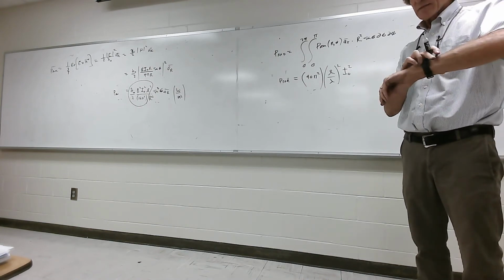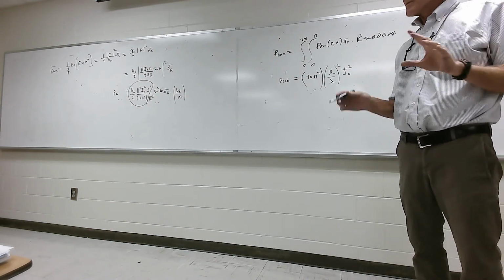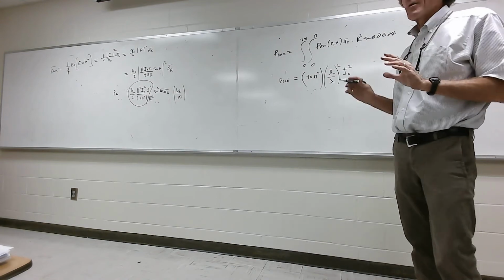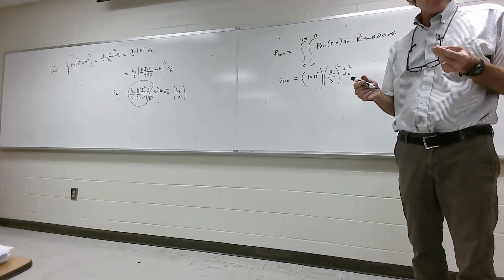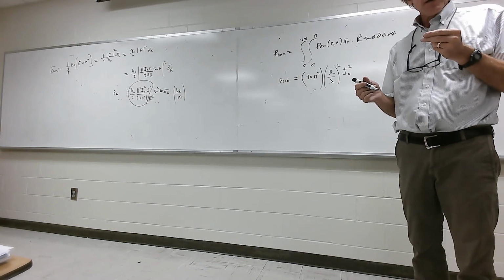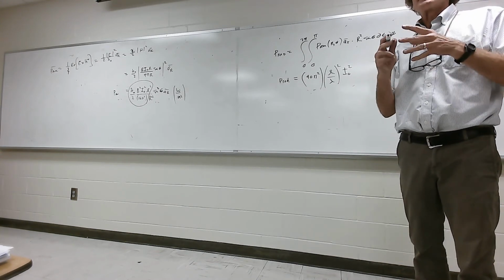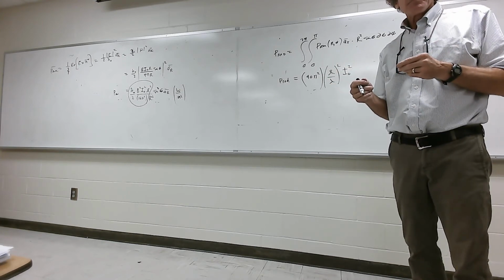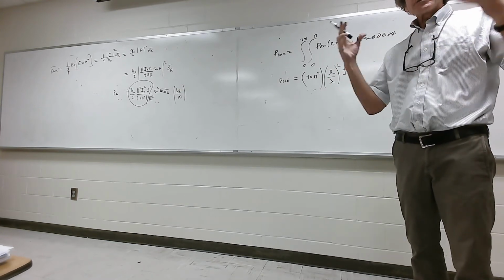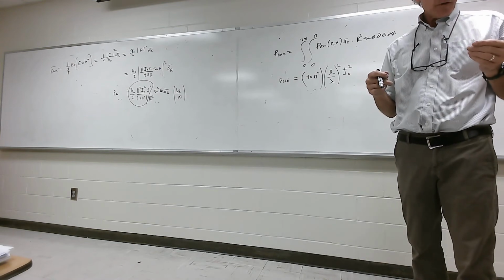Please hear me on this one. This is important, what I'm about to say. Now remember, this is an antenna. We're talking about power radiated. It has to come from somewhere. It comes from the antenna current driving a real resistance. But that resistance isn't an ohmic dissipator. It doesn't dissipate in terms of turning the electrical power into heat. What it's doing is launching electromagnetic energy. Got me on this one?